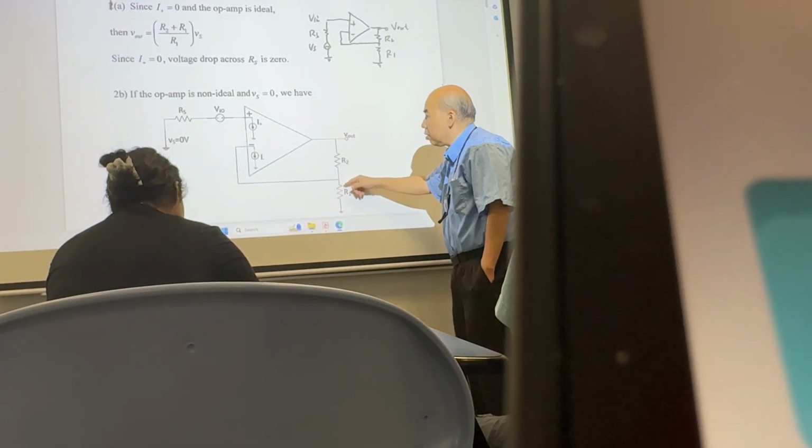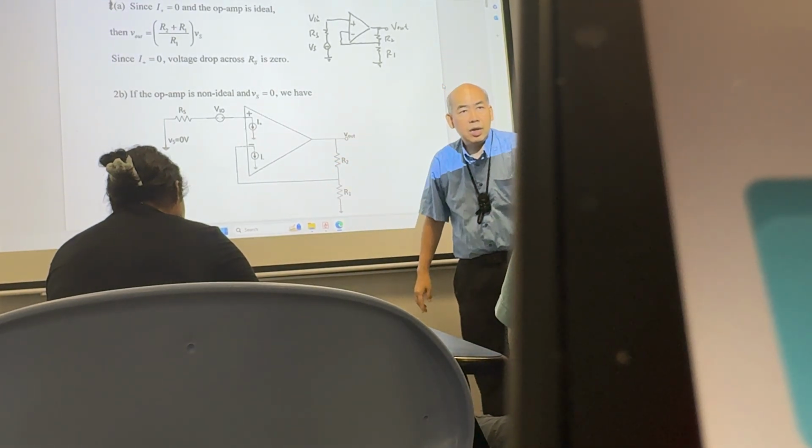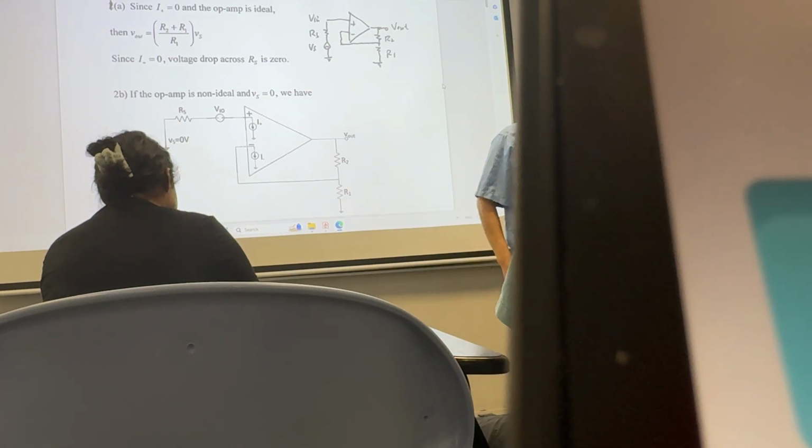You amplify it. Now how do you analyze it? How many sources? 3 sources, right? So you have to draw 3 pictures, to analyze 1 by 1, and sum them together using the superposition theorem. Now, superposition theorem only applies for a linear system.